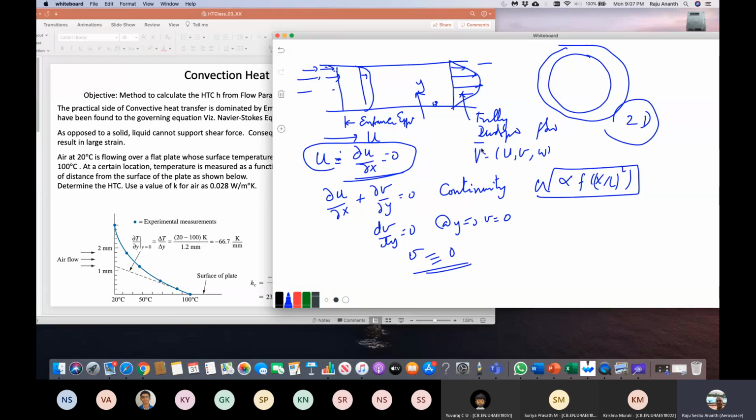We'll prove all that, but the point I'm raising is that getting an analytical solution for the heat transfer coefficient for a general flow field is not possible. So people have conducted experiments, done it empirically, and found out what the heat transfer coefficient is for various situations: turbulent flow, transition flow, and so on, and even the entrance flow, and what kind of parameters you need to consider.